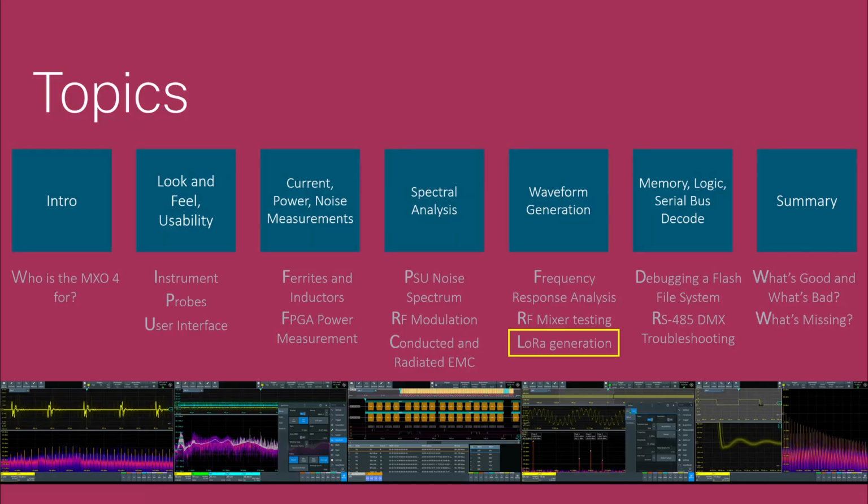So far, I'd only generated sine waves with the MXO, but I wanted to try the arbitrary waveform generation too. There are built-in waveforms, or you can capture the current displayed waveform from the scope and then replay any part of it. Displayed waveforms can also be exported and modified. The file format is CSV.